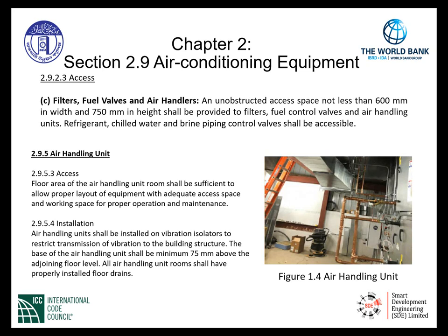During maintenance, you may have drain down procedures, and you need a floor drain properly installed in the air handling room to provide routine maintenance that may need drainage as well. Additionally, there may be condensate drainage to pipe into the floor drain as well from the evaporators that may be installed within air handlers in air handling rooms.